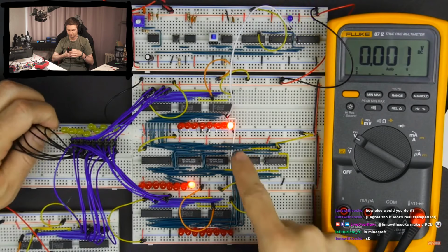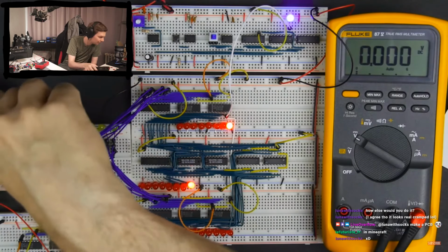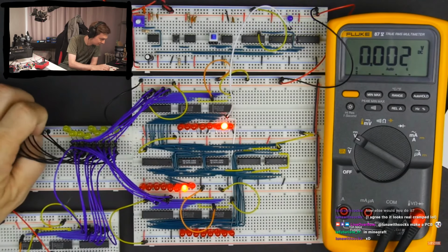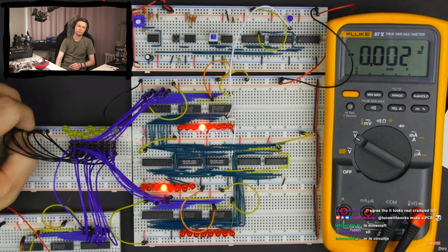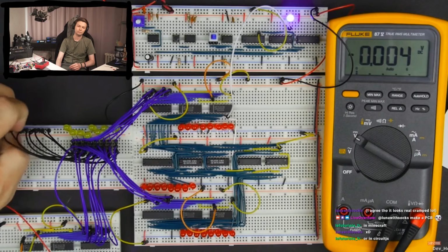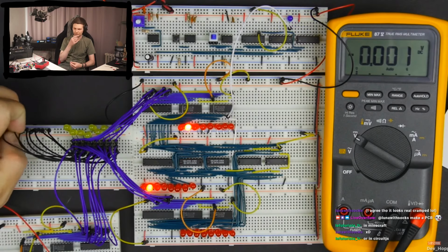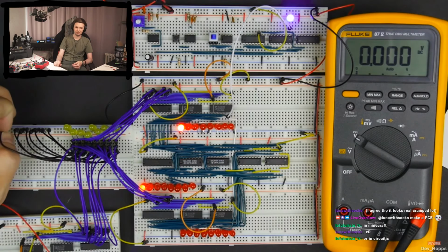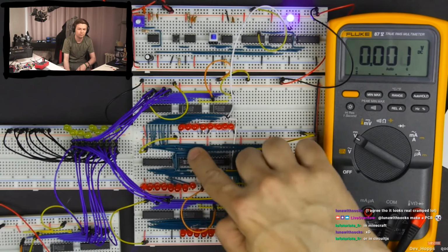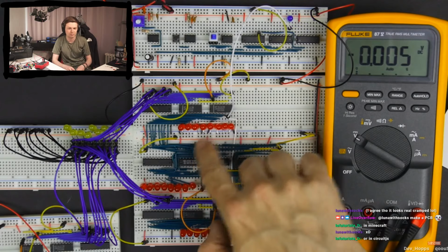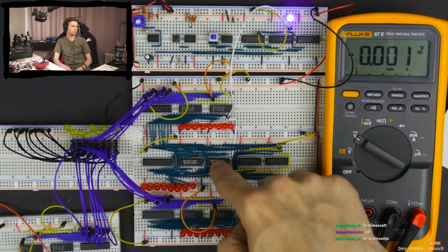So got the first bit, second bit, third bit, fourth bit, fifth bit, sixth bit, and then the seventh bit, which we just fixed, and then the eighth bit. Nice. Okay, so we found and fixed one problem here with our A register connecting to the adders.